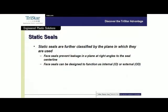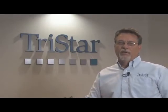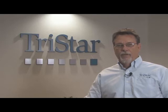Now, static seals can also be classified according to the plane in which they're being used. Face seals prevent leakage in a plane at right angles to the seal center line, and they can be designed to function as both an internal or external face seal. Internal being a seal face that is producing a block of pressure from the inside of that seal, and conversely, in an OD pressure situation, it would be an OD face seal.